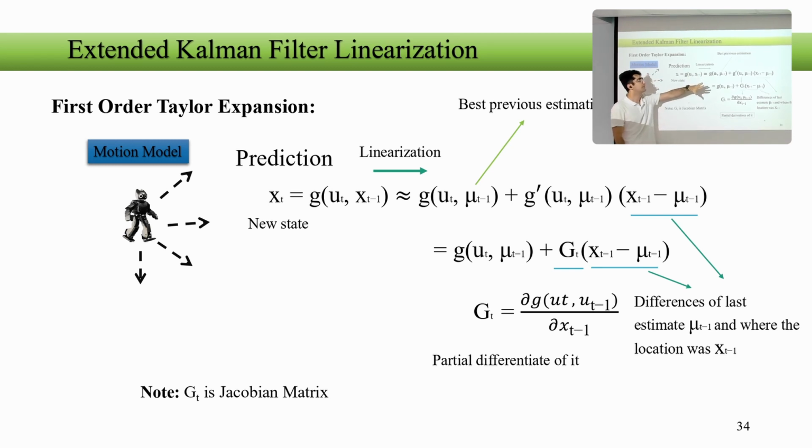What we need to do, in fact, is that the xt for the motion model as g can be written as this part over here, simply. So you only need to consider that, okay, instead of the matrices in the Kalman filter, in the extended Kalman filter, we are going to replace it with g of the control command and xt-1, and this term is equal to this term over here. The whole discussion's background is using the Jacobian matrix in order to linearize it.